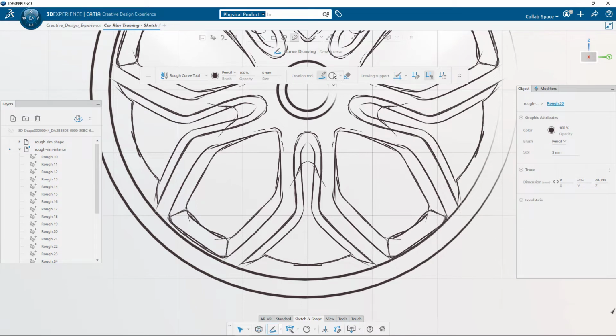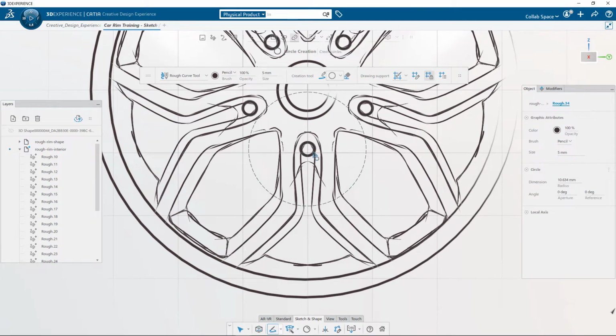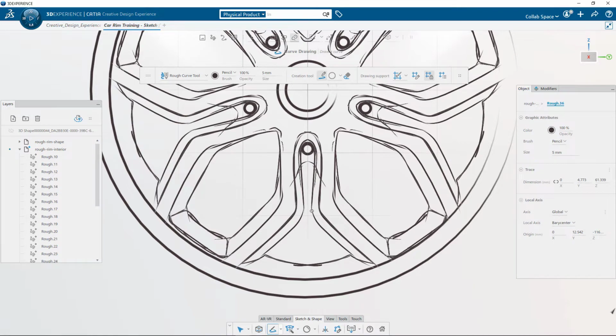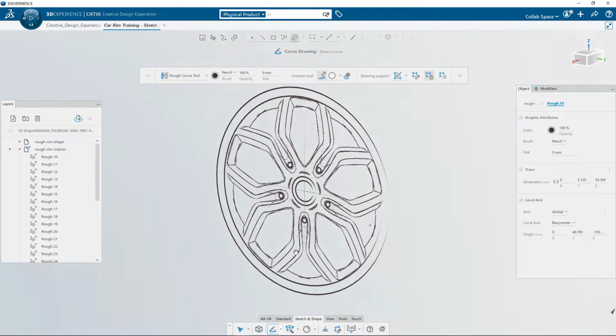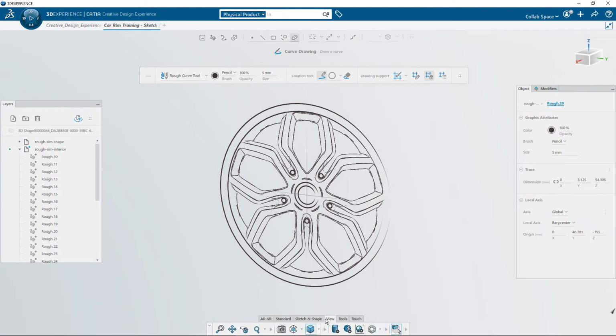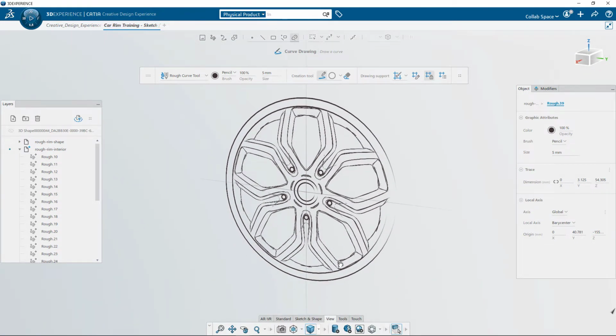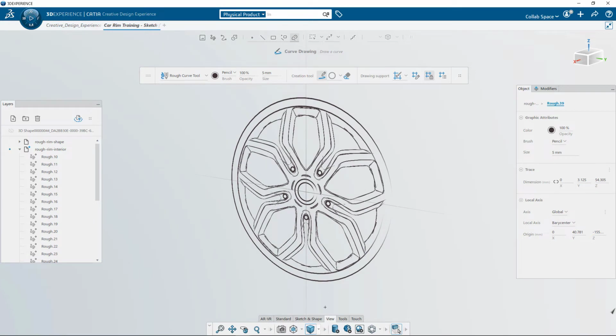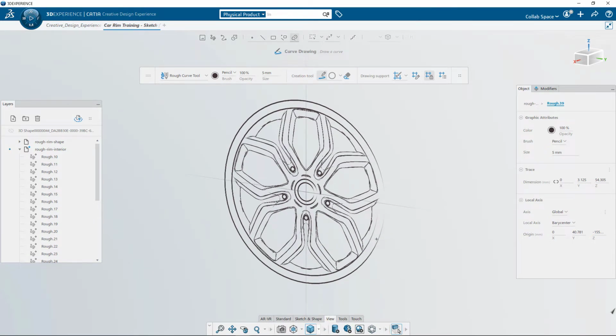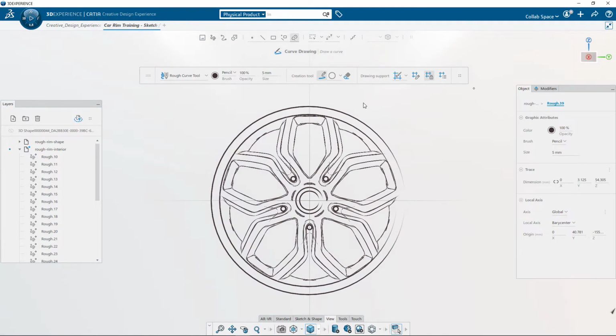I add a circle with circle primitive and adjust its dimension through the Object Properties panel without leaving the sketch command. I can easily, like that, switch between primitive or free drawing mode. I want to switch to perspective view to appreciate the result. Then I go back to parallel and on the front view with the VNAV widget.